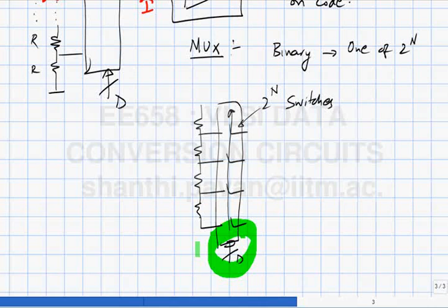For example, if you're trying to build an 8-bit DAC, you need to take 8 lines and generate 256 output lines, and one of these 256 output lines goes to each one of those switches. So you can see that it's a pretty massive affair. An easier way would be to divide and conquer, right? So you have 8 stages of divide by 2 type stuff. So you have a tree type mux.